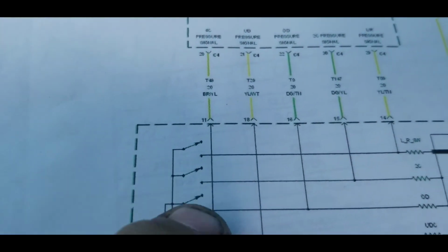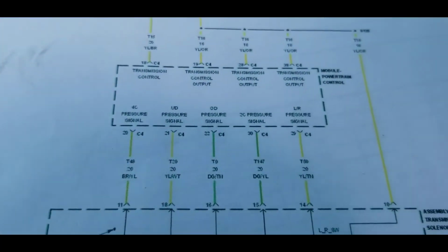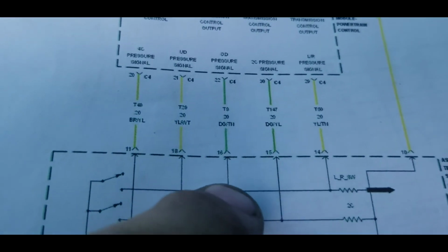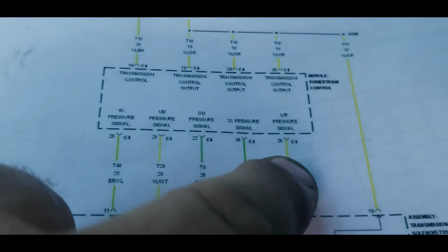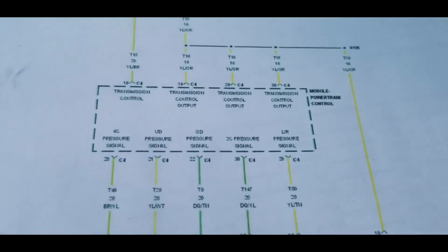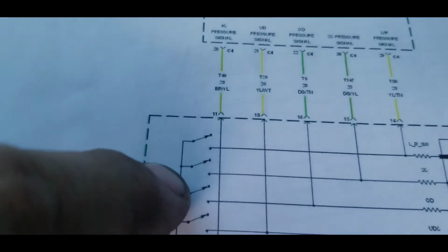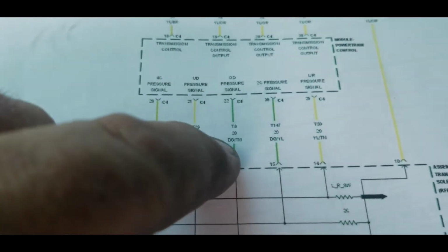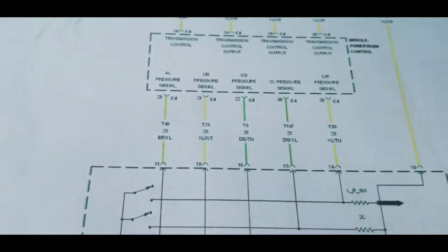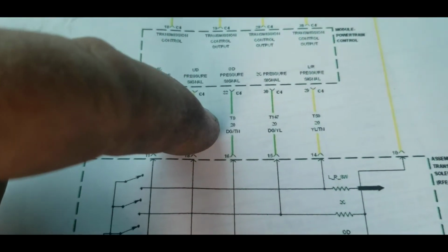When pressure hits these pillow switches inside the valve body of the transmission and pushes them to ground, this potential voltage goes to nothing. It goes to ground. The computer sees it go to ground. These five switches are how the computer knows that when it told the 2C clutch to turn on and the other clutch to turn off, fluid pressure goes away, opens these, other ones turn on, and so you have a different pattern of which ones have power at them and which ones don't have power at them. That is what the computer means by rationality.